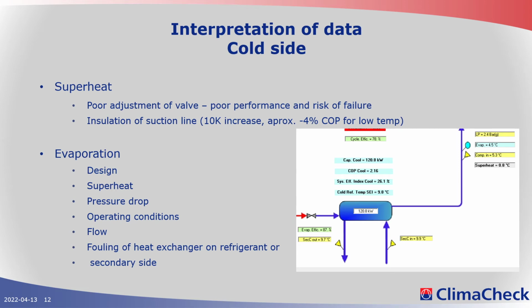So then if I go down to my cold side and look, we are measuring our chilled water or air temperatures, inlet and outlet. We are measuring our evaporation pressure, and we are measuring the temperature on the inlet. If I have long suction lines, I can add a sensor to measure the evaporator outlet, because that is typically what the expansion device is sensing if I'm using an electronic or thermostatic expansion device.